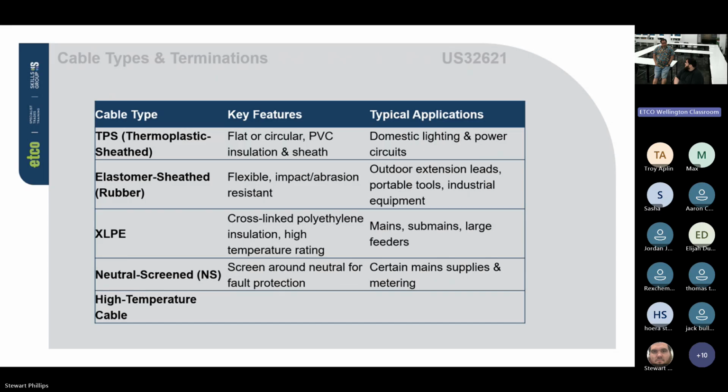Do you get given 3008? No, you get a snippet out of it. So in your exam, there'll be a little table that you open up and that will give you the additional parts to get the information from it. If I remember correctly, on C4 is a simplified volt drop, and just above it is your volt drop formula. So that will be there, and then you'll get a snippet of 3008, and then you'll get access to table 42, 11, 13, 27.1, and 27.2.